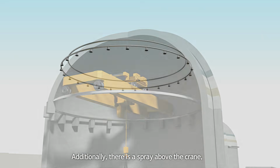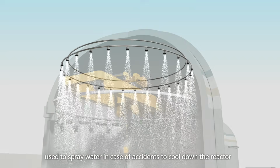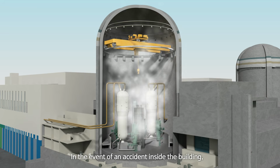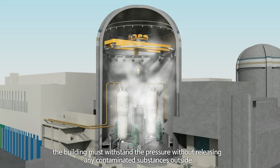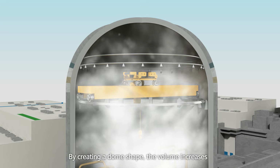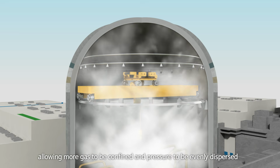Additionally, there is a spray above the crane, used to spray water in case of accidents to cool down the reactor. The interior of the dome is mostly empty. The dome shape is designed to evenly distribute pressure. In the event of an accident, the building must withstand the pressure without releasing any contaminated substances outside. By creating a dome shape, the volume increases, allowing more gas to be confined and pressure to be evenly dispersed.